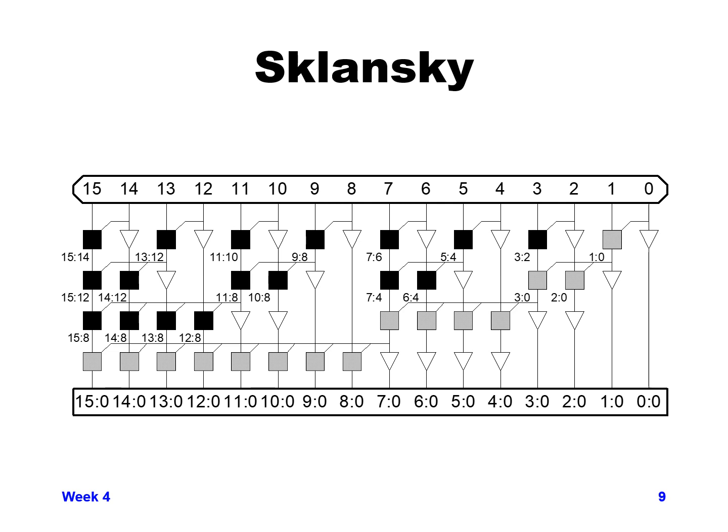So a different adder tree is the Sklansky adder tree, and this one has a benefit of basically computing the large group PG functions along with the small group at the same time. So you can see there's actually a smaller number of stages through this.